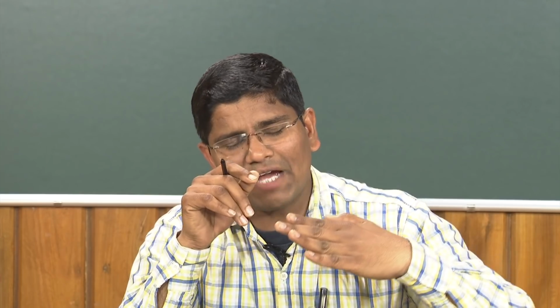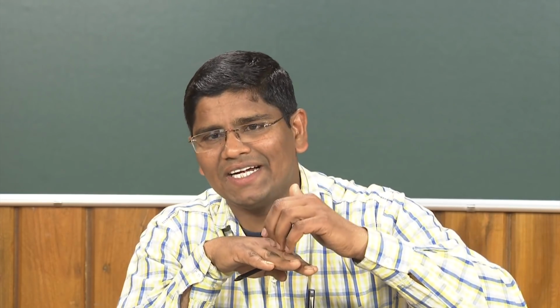So, what will happen if I have a soft workpiece material whose chip is continuously flowing on the surface? In that circumstance, the chip is carrying, as already told, 80 to 85% of the generated heat. So, it tries to weld its internal layers nanometer by nanometer on the tool surface, and after some time, because of the friction and high temperature of the chip, this temperature goes inside the tool, and the thermal softening of the tool takes place, and at a certain point of time the tool's top layers will go off. That means crater wear, which I just showed, takes place.